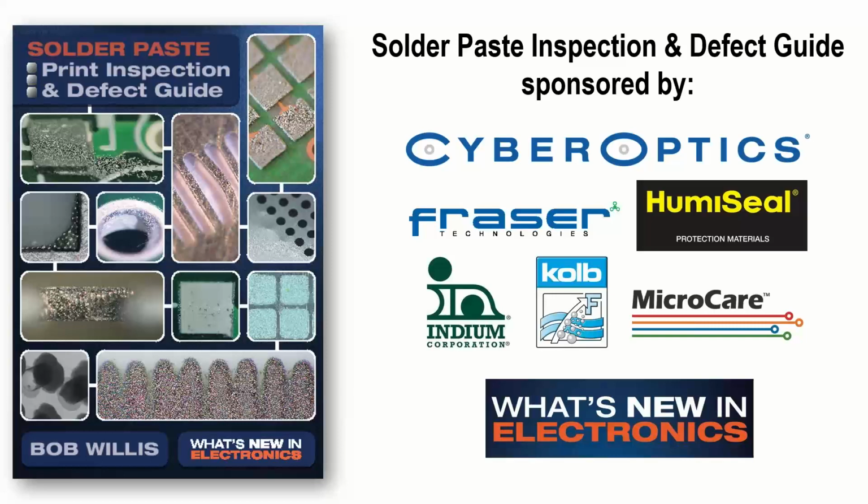Will solder paste go bad with excessive mixing? If you take a solder paste and mix it and mix it and mix it, and particularly if you mix it in one of these automatic mixing systems, it will change the characteristics of the material. So it won't make it go bad, but it will change, I would suggest, the viscosity of the material. And some solder paste manufacturers recommend using automatic mixers, and some do not recommend automatic mixers. So I guess it's based on their own experience.